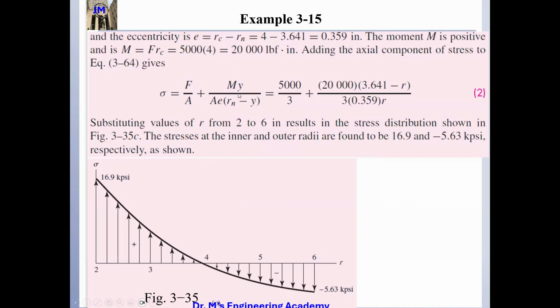So that's the reason. And when we calculate the stress, this F divided by A is the tensile stress. Here it is bending, and because of the bending moment we have a stress. This is also a normal stress, which means perpendicular to the surface. That's the reason we can put these two together. Right? So you can see we can just draw a curve, put these values inside here. We can see the sigma is changing with respect to R.